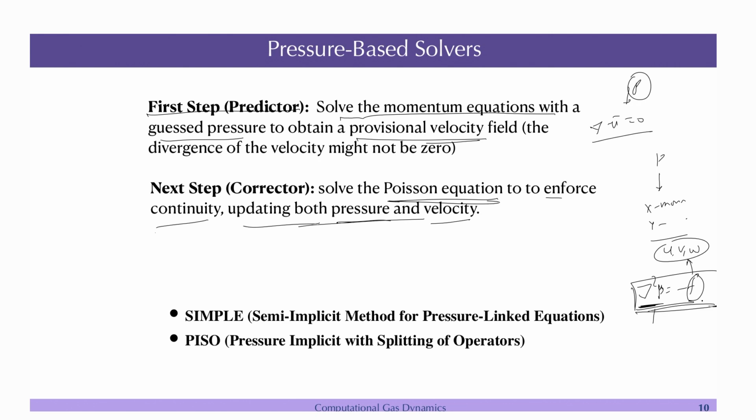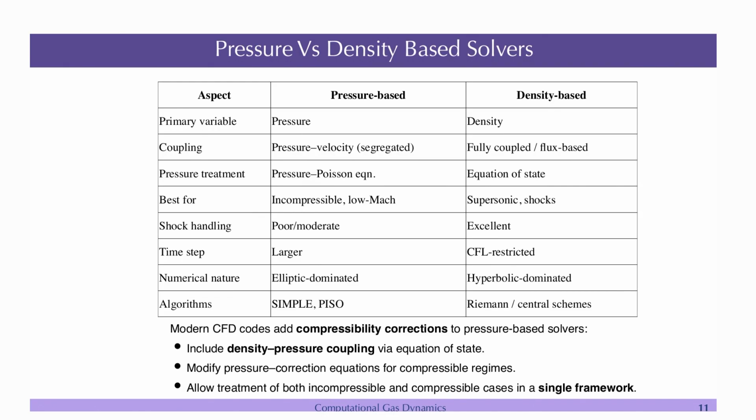There are several approaches to do that. There are schemes like SIMPLE, the semi implicit method for pressure linked equations, or the PISO scheme, the pressure implicit with splitting of operators, where you basically split the operator. These are used in pressure based solvers. I will not say incompressible, because there are certain solvers which are pressure based, but you can actually implement energy equations there, and you can also solve the compressible problem with them. These are called pressure based solvers.